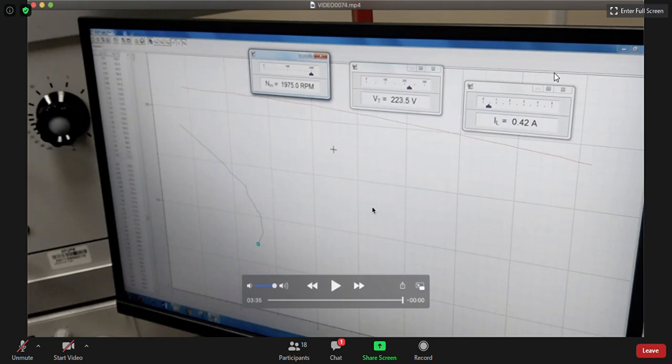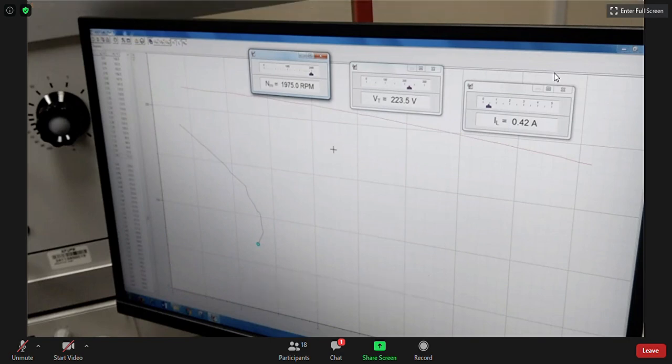You must understand the difference between the shunt generator characteristics and the cumulative and shunt both. Sometimes we give you two graphs and ask you to identify which one is the shunt generator and which is the cumulative compound. Very immediately you can say that the top curve is cumulative compound and the bottom curve is shunt, because of the characteristics.